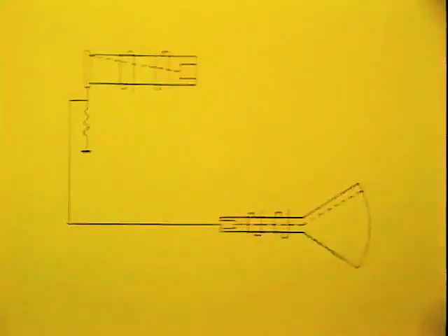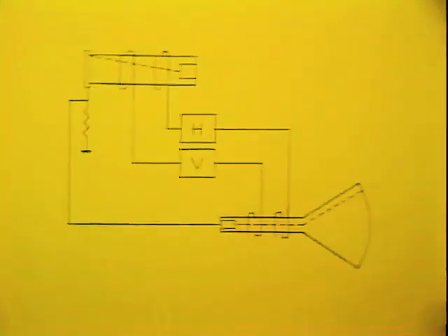The beams are synchronized, or kept in step, horizontally by using the same signal to simultaneously drive the scanning coils around the camera tube and the picture tube. The actual signal is generated in an oscillator. The vertical movement is produced in a similar manner. Another oscillator produces a signal which is simultaneously fed to both sets of vertical coils around the camera tube and the picture tube.